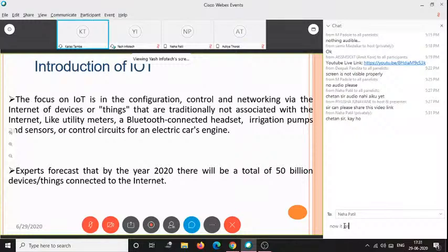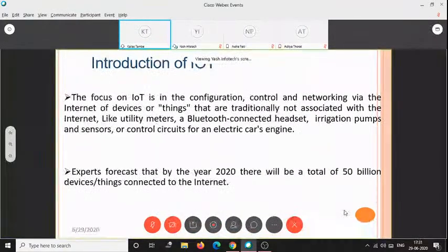And here you can see one more thing. You know that nowadays the temperature is rising day by day. So in a controlled environment, in a greenhouse or polyhouse, sometimes they need foggers also when the temperature hits some threshold value. Let's say for a particular crop there is a range of temperature. If it goes beyond that, then the foggers will start automatically, and it will bring the temperature down, right? So this was the example.